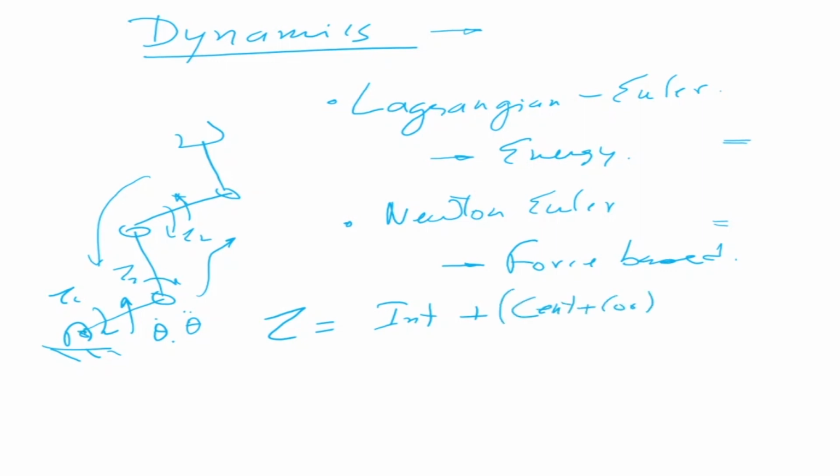You can imagine here that there is one link which is rotating on another link. Let me just draw two of them, one here and one here. When this is rotating with a velocity theta 1 dot, this could be rotating with a different velocity theta 2 dot. So this rigid body, which is this link, has another rigid body which is rotating with a different angular velocity. Basically it will be subjected to a Coriolis force also. It is like a body here, and there is something which is rotating on it. This is also rotating and that is also rotating, and because of the differential angular velocities, it will have a Coriolis force. Now there is a centripetal force because this is rotating.